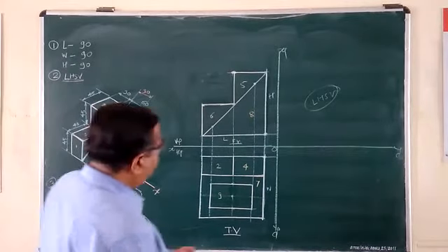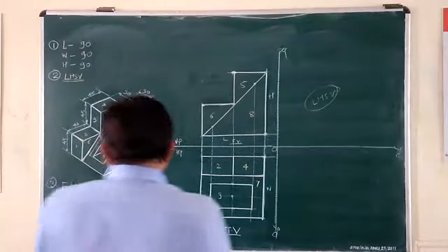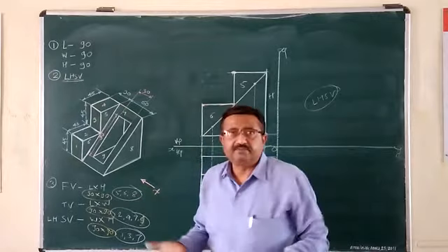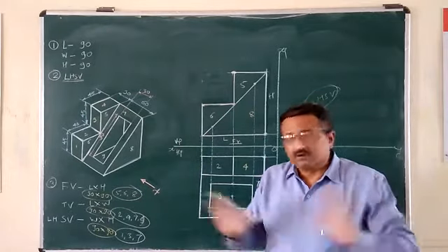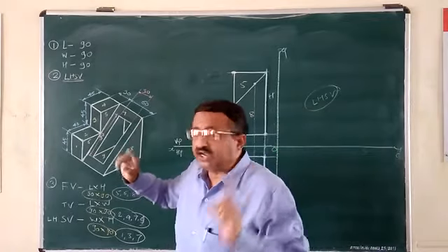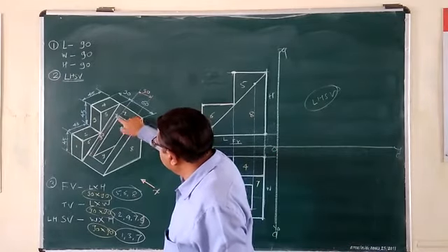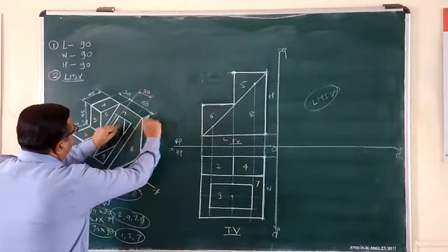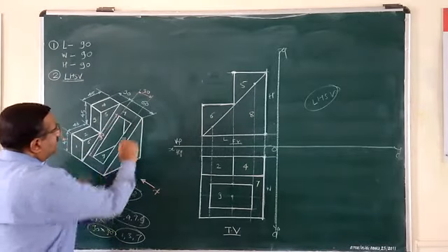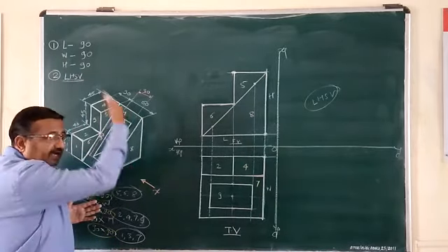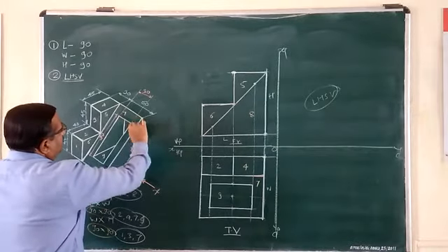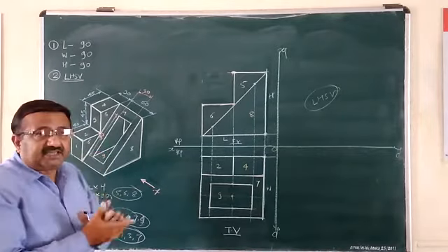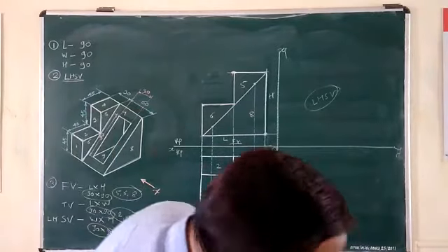Top image. Now, just tell me whether in the direction of x, this hole which is cut rectangular in this surface, whether it will be visible to the observer? No, not at all. Four corners have been created due to that cutting. First corner, second corner, third corner, fourth corner. This is the visible corner. These corners run from all these four corners of this rectangle till the end of the object, the extreme surface. Those corners are not visible. So the effect of the invisible thing, that is dashed and thick line, one should give here.